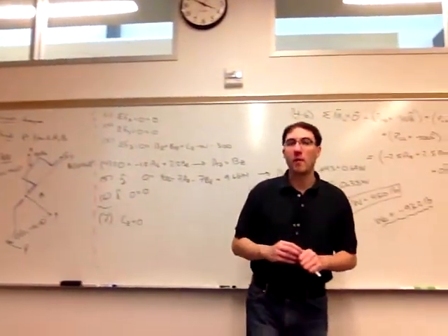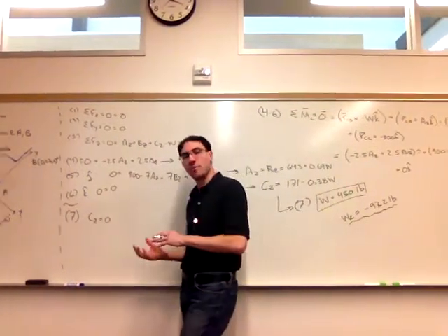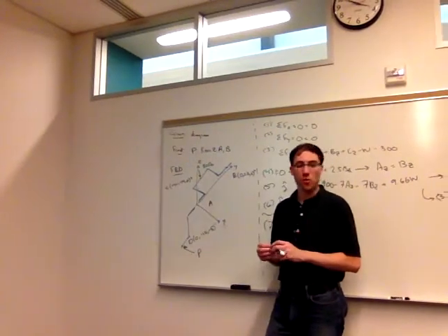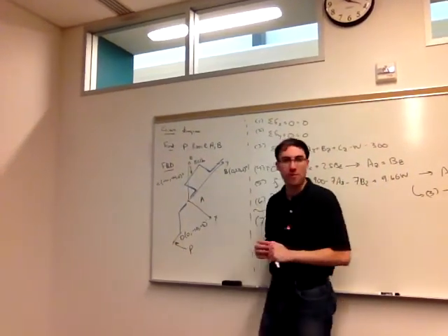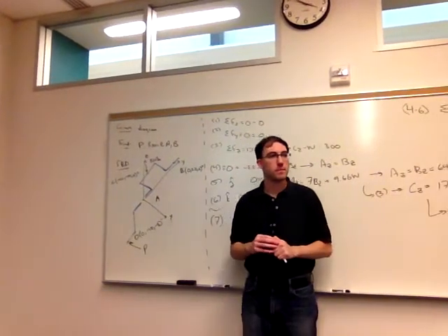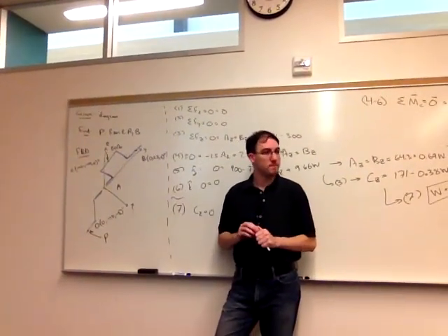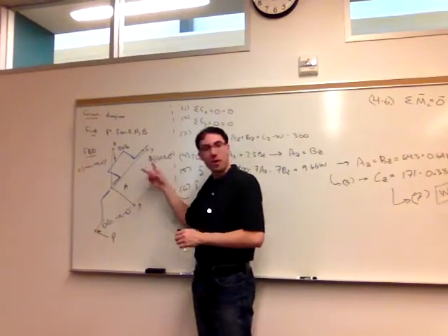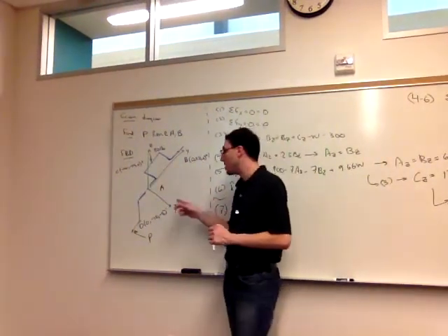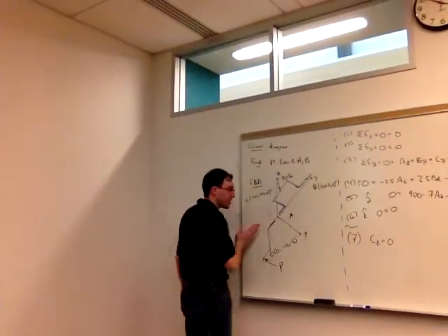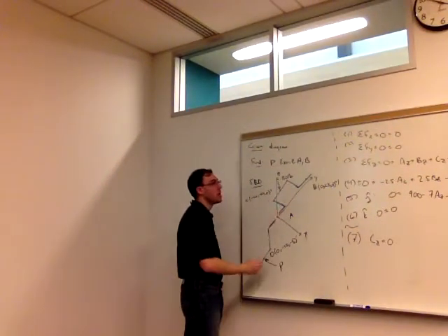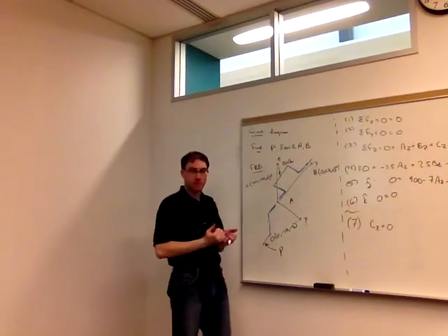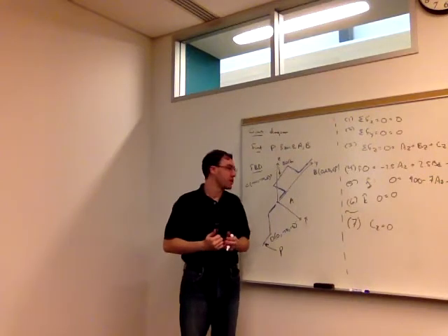So A and B are both bearings, but again, there's a difference between a journal bearing and a thrust bearing and what motion they allow. So A, they say, is a journal bearing. So how does the journal bearing differ from the thrust bearing? Right, so as far as where they differ is the translation of the shaft. A journal bearing, the shaft is allowed to pass in its longitudinal direction through it. In a thrust bearing, it cannot. It's halted there. They both provide forces perpendicular to the direction of the shaft, though.